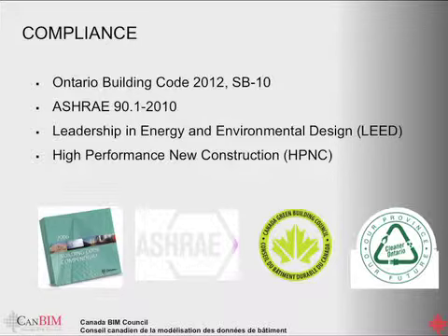Compliance, I don't want to talk too much about compliance, but basically the Ontario Building Code has now upped their game. If you have a 40% glazing building, you have to beat ASHRAE by 5%. I don't think they have the resources to check all those energy models, but with ASHRAE 90.1, 2010, things are getting tougher and tougher. It's getting harder and harder to meet these compliance reports, and this is where LEED has been a big driver of what we do. It's been pushing the boundaries.